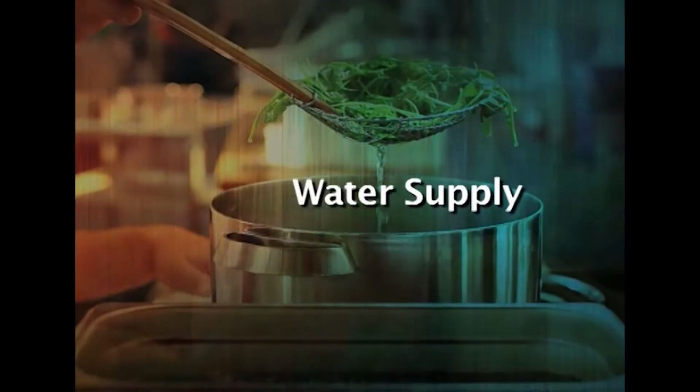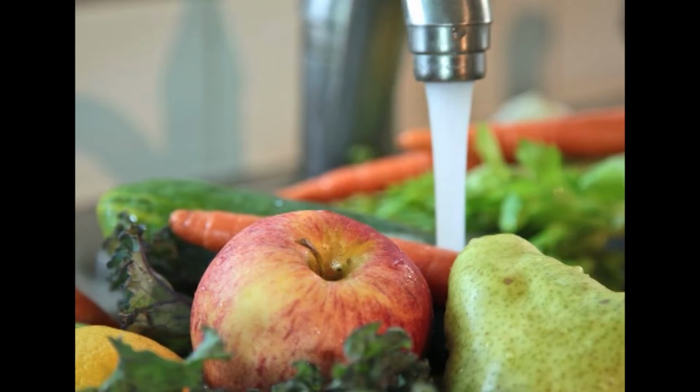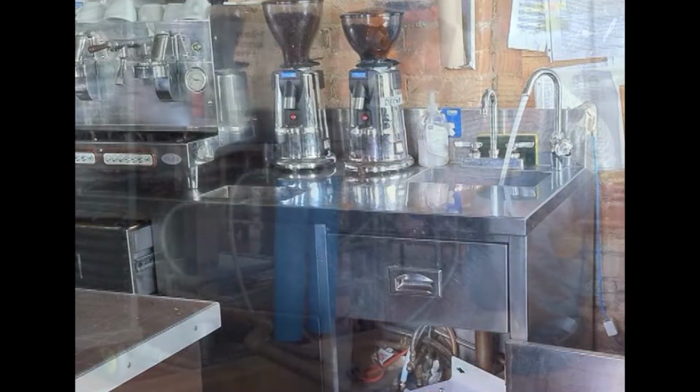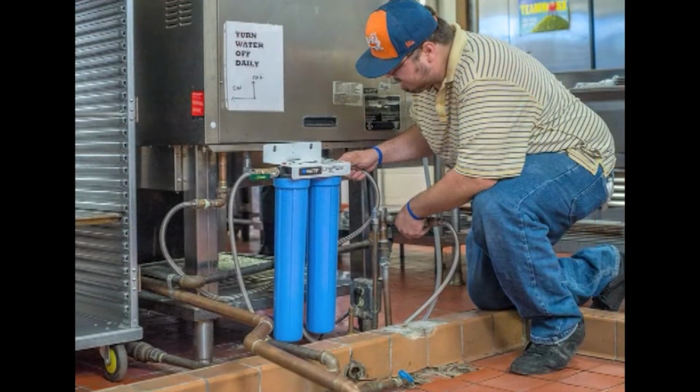And for water supply, generally it is advisable to have soft water supplied, and proper care should be taken that the microbial count of this water is minimal. Hard water should not be used, because if hard water is used, staining of the vessels can happen and it results in the spoilage of the equipment. Usually what we see is, if you use hard water, you see scaling on these vessels. Because of the scaling, heat transfer is greatly reduced and more fuel may be required.